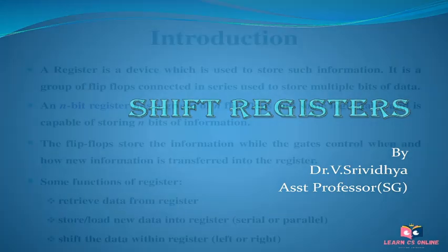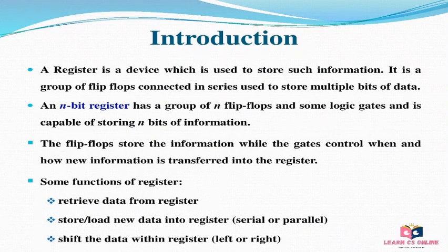A register is a device which is used to store information. It is a group of flip-flops connected in series used to store multiple bits of data. An n-bit register has a group of n flip-flops and some logic gates and is capable of storing n bits of information. The functions of registers are retrieving data from the register, storing or loading new data into the register, and shifting the data within the register either left or right.